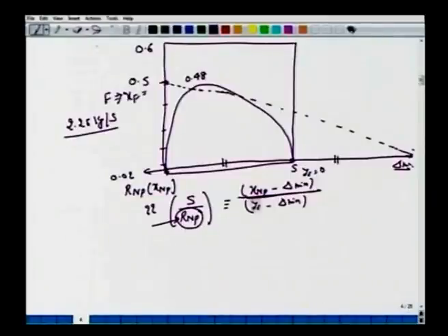That means we should make use of those quantities, let's say F here. Now the tie line which passes through this and through this here will intersect at E1. Here we have extract and here we have raffinate. This tie line which goes through this, let's say we have Y1, which if you notice is 0.39. Now how do we get this minimum amount of solvent?